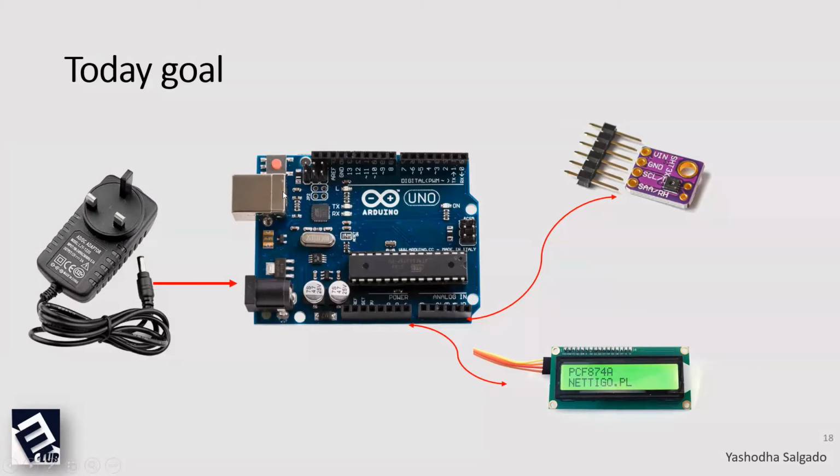We are not using the entire Arduino board. We just take the Atmega microcontroller and its necessary components from the Arduino board and those things and the sensor. I put it into a single PCB and make a power port for the 12-volt supply.